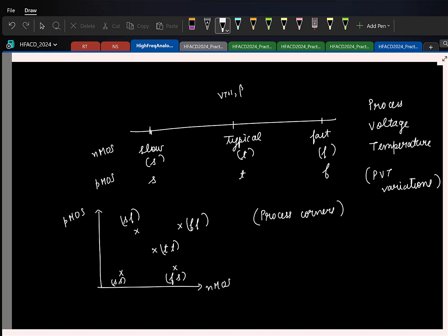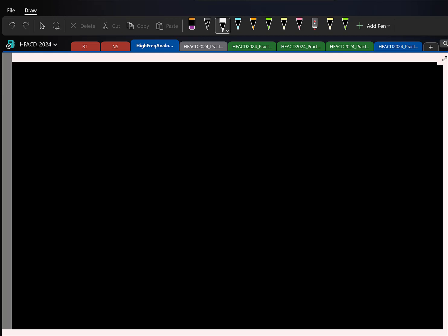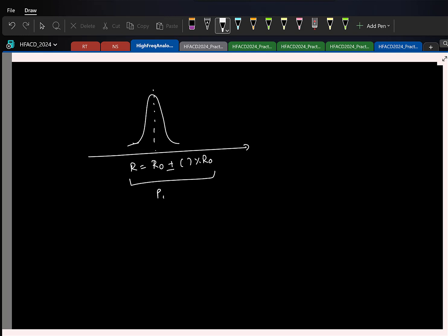Cool. So, basically to summarize, if you have any component value you take, within a chip you will have a variation, right? And the mean value, let's say if I take for a resistor, the mean value you expect it to be some nominal value R0, but due to process variation this will change to plus or minus some percentage of R0. That will be the nominal value, and this is due to the process variation, right? And a typical number for this variation is say 10 to 20%.